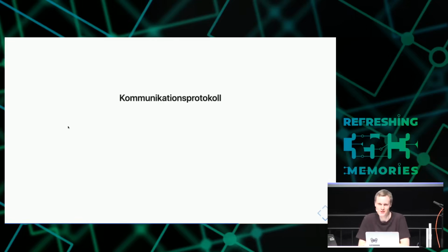And it would be a good idea to use something like this for a generic storage way for what someone put into a keyboard, and then bring it to a hardware device. So our current idea is to use MIDI, which is a serial protocol, over the UART port, going to the different devices. If you don't know what this means, it's universal asynchronous receive and transmit.